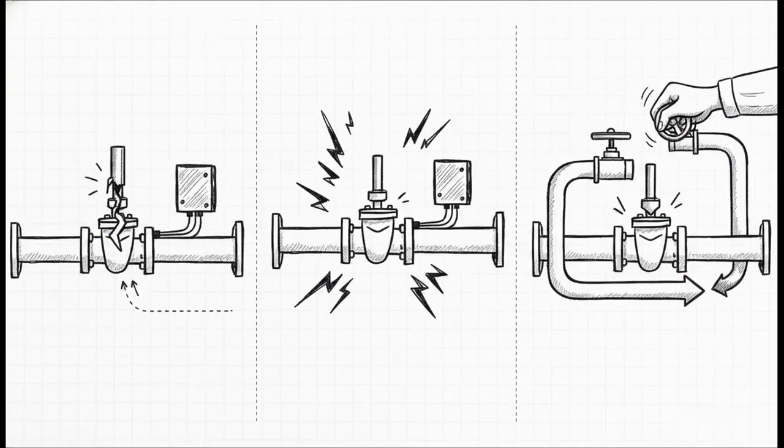We really need to thoroughly analyze the mechanical realities of control valves. They are not magic pressure walls. They are physical mechanical devices with moving parts, stems, plugs, seats, actuators, and they do not always sit exactly where you command them to. First, evaluate the valve failing in the open position. Whether it's an air fail open design losing instrument air, an actuator diaphragm rupture, or simply a mechanical sticking of the stem due to debris in the line, the result is exactly the same. Downstream pressure will rapidly rise toward the full upstream pressure with almost zero frictional drop.